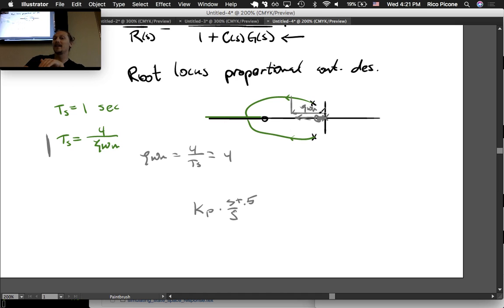Yeah, well, it's your second order approximation. You're pretty much throwing it out the window at this point. But you're saying, okay, I designed the proportional controller to be pretty good transient response wise. As long as I have this 0 in there and their effects kind of cancel, pole 0 effects kind of cancel, but not exactly, hopefully I won't mess up my transient too bad. So that's the idea. So we'll put it in as a compensator.